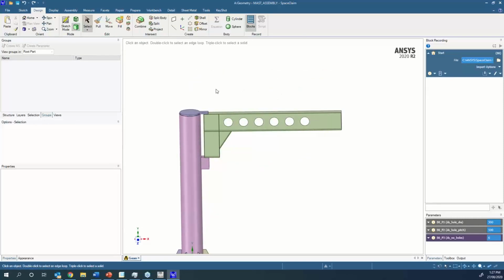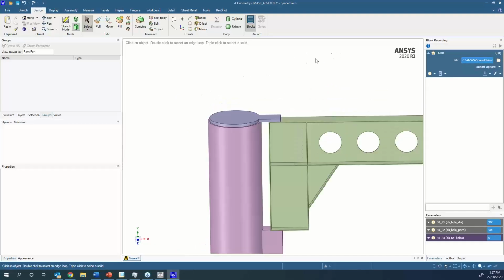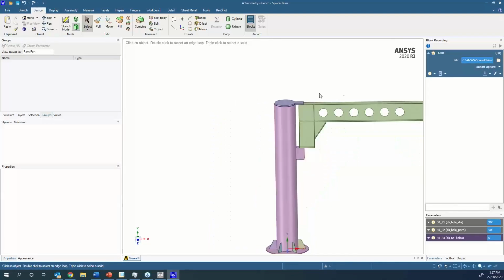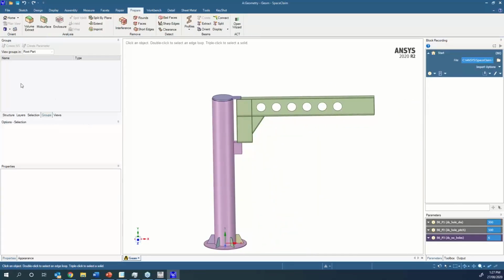This is another candidate for mid-surfacing, so let's do that. We'll pick out a couple of, I think this is probably our biggest gap to fill here. This is 40 millimeters. So again, when I go back to the Prepare tab, this will be an area where I would say mid-surface, use range, and I've forgotten what it was. I think it was 40. So let's say 45.